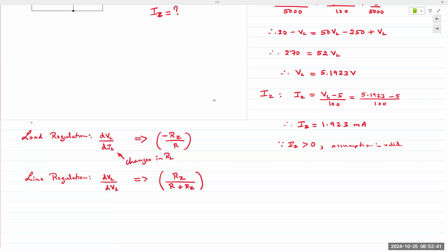There is, of course, a whole lot more theory and other factors that we can use when we design. But at its simplest application, if you put it all together, then you can design a DC power supply by taking, let's say, a transformer. The transformer steps down the power outlet voltage, let's say from a 120 volt power outlet, down to 15 volts. The 15 volts can be given to, and I'm just throwing out some random numbers, a bridge rectifier circuit.